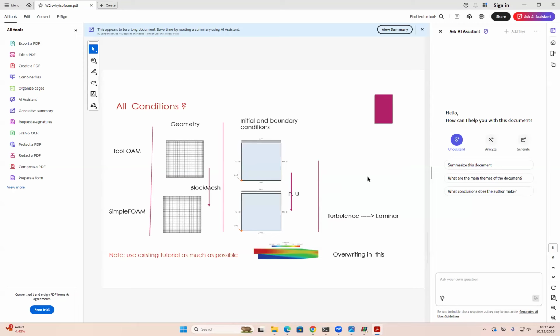In any software, if you want a structured mesh with less skewness, we have to minimize the circular or arc parts. We can keep the hexagonal shape as much as possible to get the structured mesh. Yes, if you have many curves or complicated geometry, the skewness will increase. So I want you to understand how you can draw this.